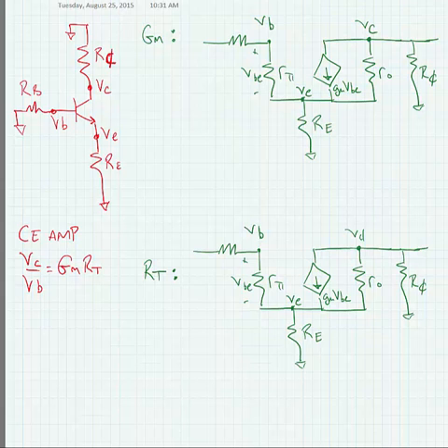What we're going to do here is short circuit the output, and find the current I out that flows into that short circuit due to a voltage input at the base of the transistor. We can figure out what to do with the other external circuitry later on. Namely, it's probably just going to cause a voltage division, and we can solve for that later. So when finding the transconductance, we put this test voltage in, measure the current that flows into the short circuit, and we would do that with KCL analysis at this node and this node.